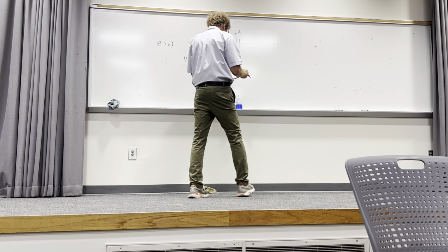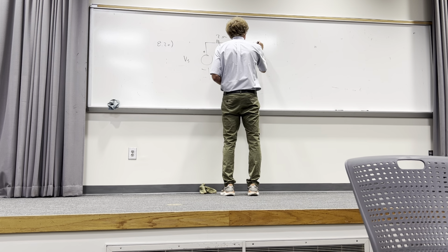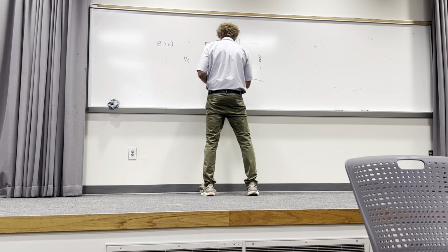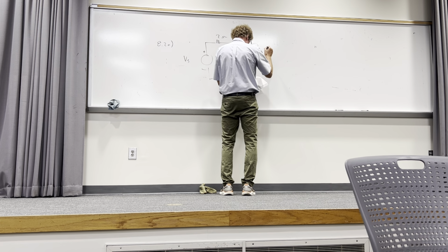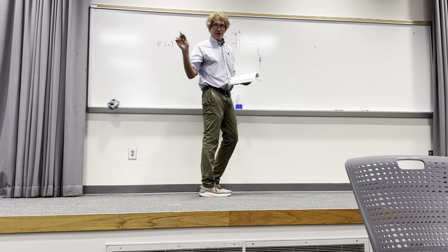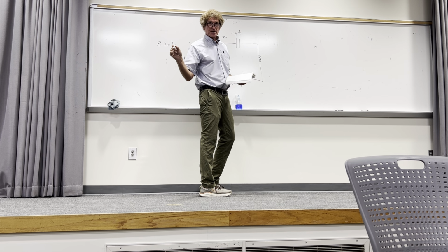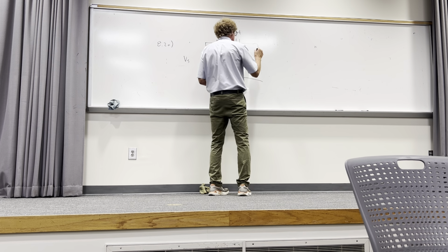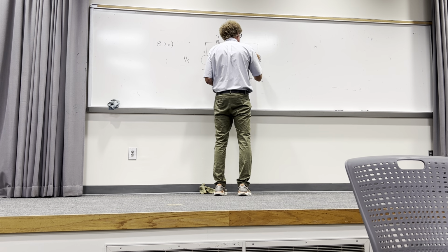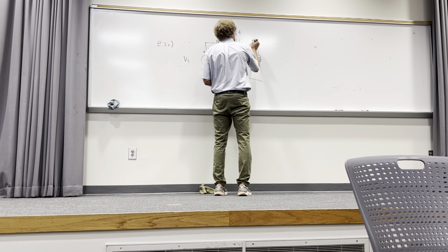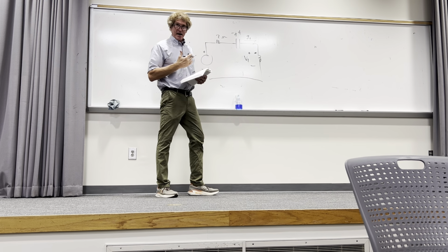So, got minus J4 here. Then, I got a transformer. Now notice where the dot is. I'm trying to tell you the secrets of doing these things so you don't mess up. The dot is critical. This is the dot. This indicates where V1 is. You need to always label where I1 is. That is the primary side.